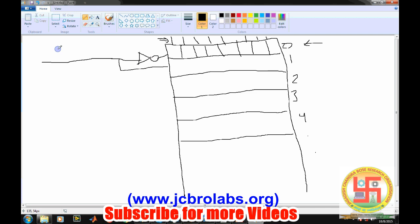Now this is a single wire. This is known as address decoding. If we put a 0 here, here will be 1 and here will be 0, so this particular address will be selected. And if we put a 1 here, then the second address will be selected, and whatever data is there will be available on the data bus if we want to read that particular memory location.